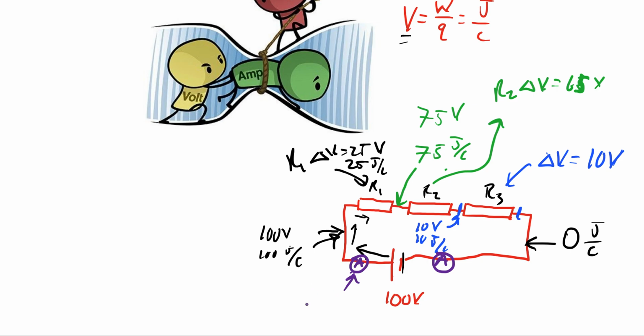If that ammeter reads 2.5 amps of current, then at the end, there have to be 2.5 amps of current. I'm not getting rid of electrons in this. I'm only getting rid of the energy those electrons have. So the current didn't change, just the energy that those electrons were carrying did change.